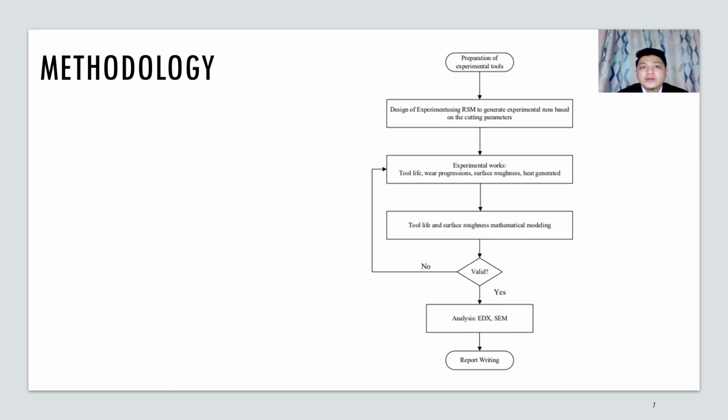The cutting tool material used is a carbide insert of ISO designation CNGG 120408 SGF, which will be used for the machining experiment. For the machining test, all the machining experiments will be carried out on a CNC lathe, the ST20, that has a continuously variable spindle speed.